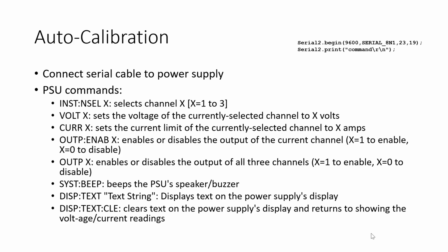So in other words, we can then map the actual voltage as we know what it is based on our instructions to the power supply. Then we can read the ADC value, which will be different than whatever the power supply is putting out, generally. And then we can build a model of the power supply internally in the code. We can construct a model that will correct the voltage we read and hopefully give us an accurate reading. Does that make sense? And this code should translate over to an actual battery.